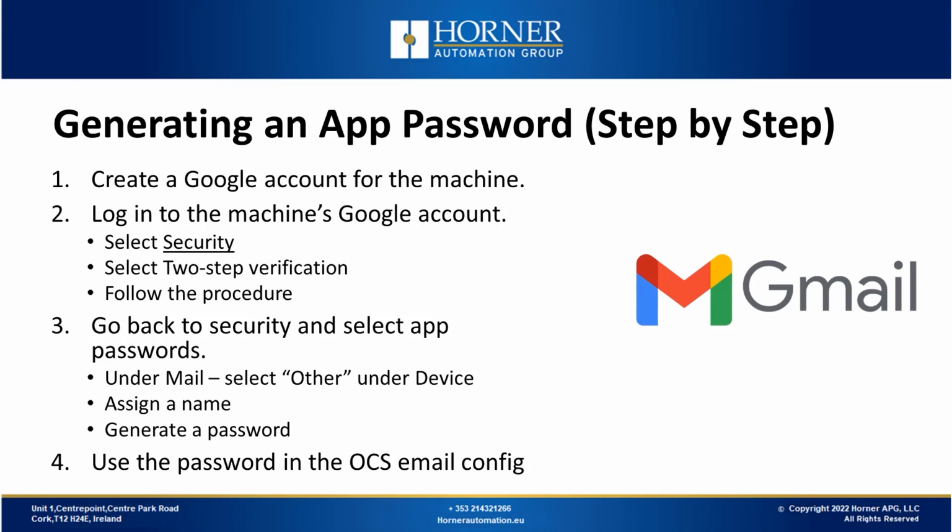There's two ways you can do that. You can hardcode the password, or if you assign a variable to the password, you can go into the OCS from the touchscreen in a protected screen you have set up and type in that new password from there. And then if it ever changes in the future, you won't have to use Cscape to make that change.